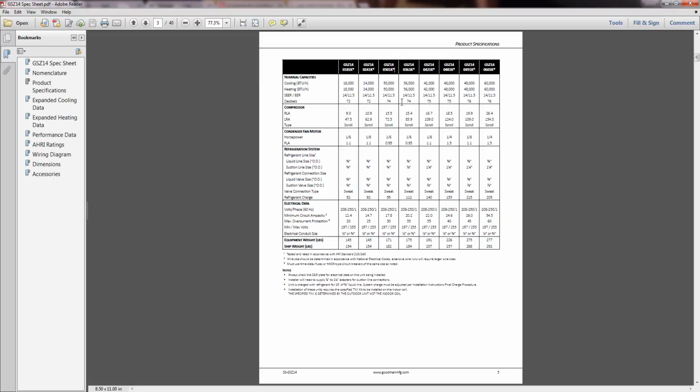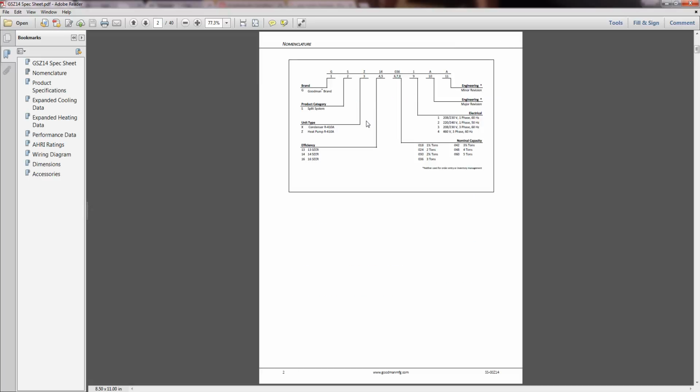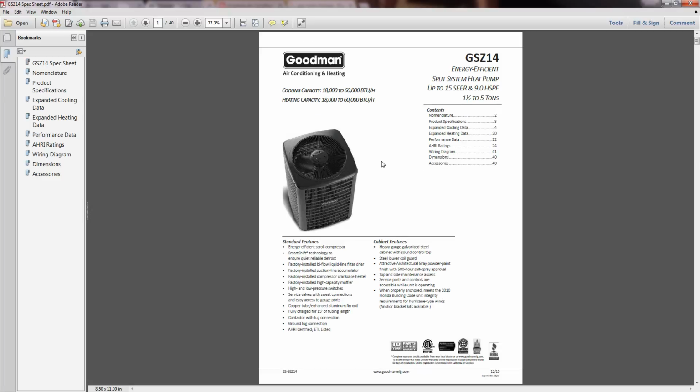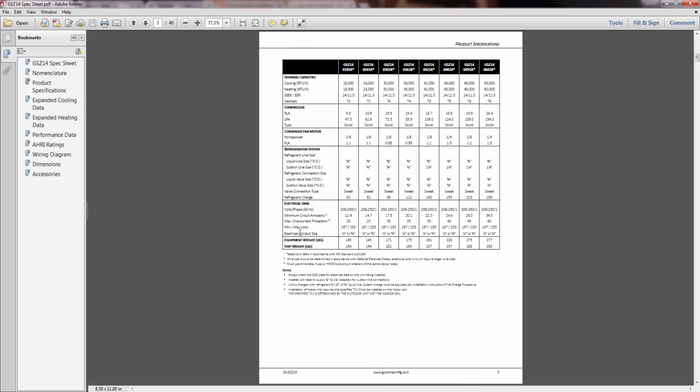Now if you're using an air conditioner only, you can also use the tonnage from your model number. Look at how many tons you have, multiply the tonnage by 12,000. That is how many BTUs you're receiving from that unit. Energy Star, same as the furnace. If it doesn't have a listed logo here or below the specifications, it is not Energy Star certified. So do not put yes, but no.